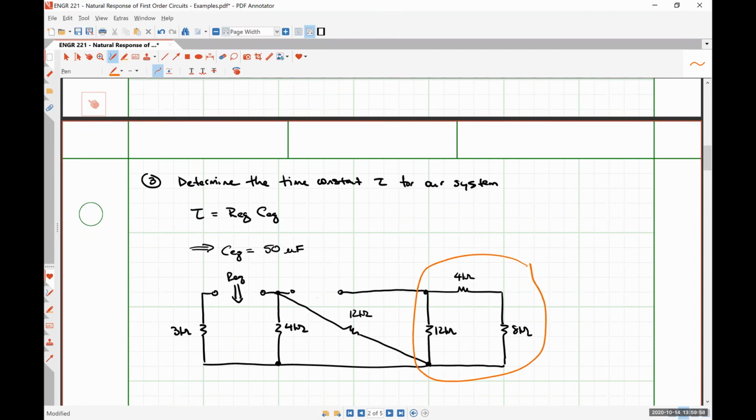Do these resistors that I've circled contribute anything to the equivalent resistance? No. As we saw beforehand, I could shrink these guys down into a single 6 kilo ohm resistor, where one leg of that resistor is open circuited, so it's not going to contribute anything. So we really are only looking at how this guy and this guy combine.